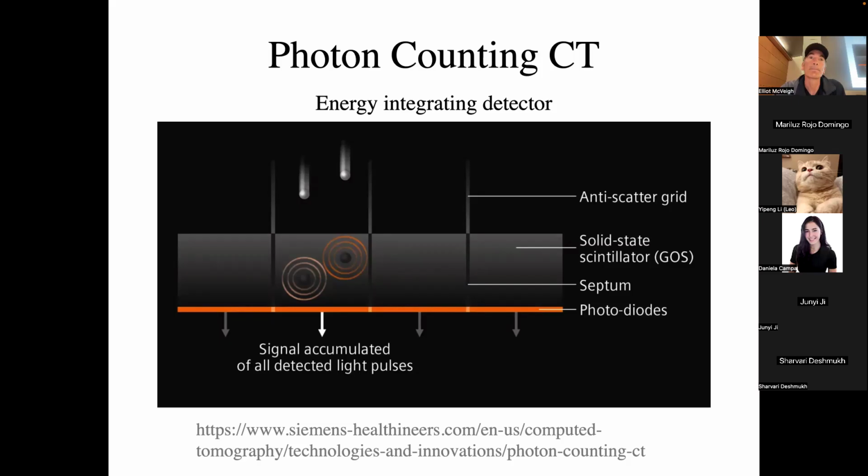What's the need for that scintillation when you're getting a digital image out anyway? Oh, the scintillation is the method by which you detect the X-ray, right? Without the scintillation, the X-ray goes undetected. So in this technology, which is 99.999% of all CT scanners in the world right now, and digital X-ray systems, the X-ray hits a material that has been designed to flash when an X-ray hits it.